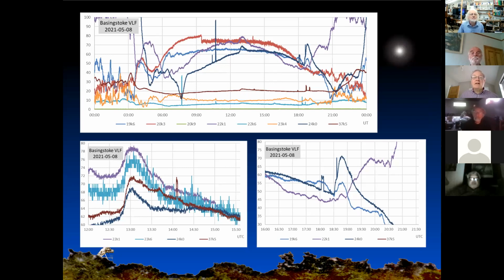During the day, things settle down, but you can see various sharp changes in amplitude. This is always an interesting time, dawn. Lots of things are happening. The sun's coming up. All that ionizing radiation is hitting the ionosphere for the first time. Initially, it's illuminating it from the underside, as the sun creeps above the horizon. So you get wild variations in amplitude as the ionization levels change and the reflection of the radio signal changes.